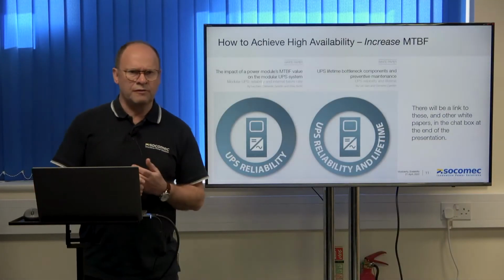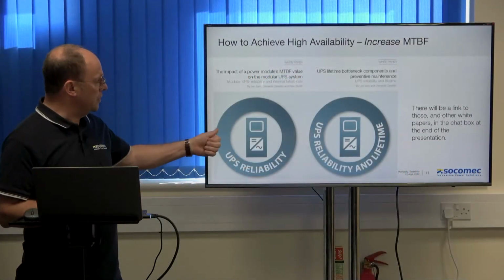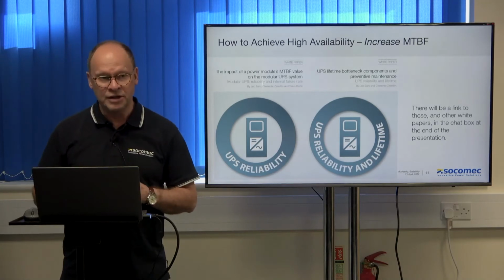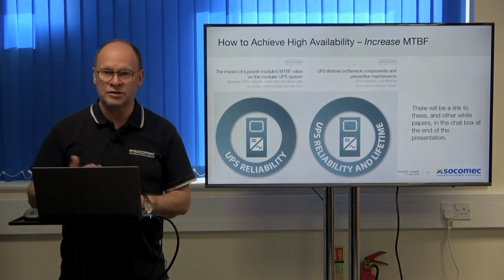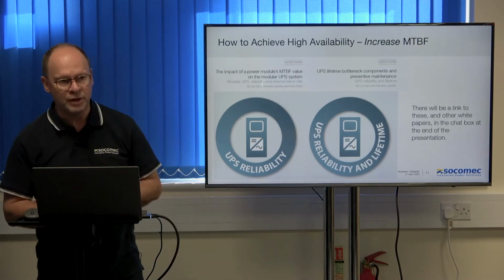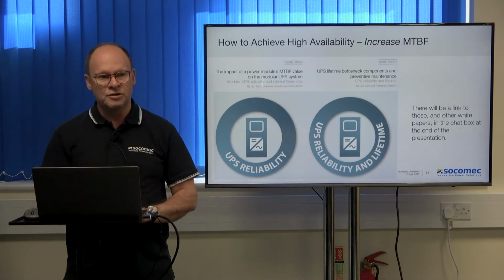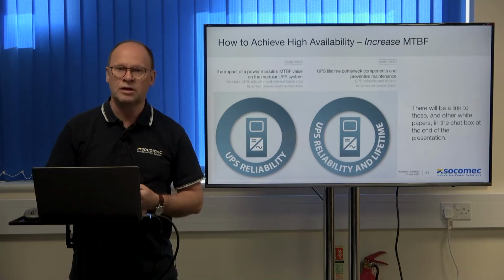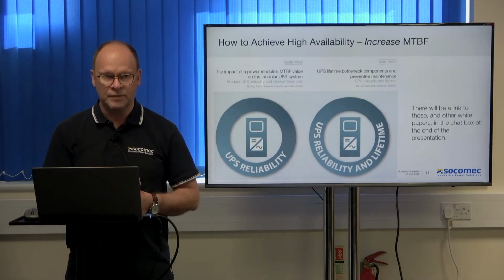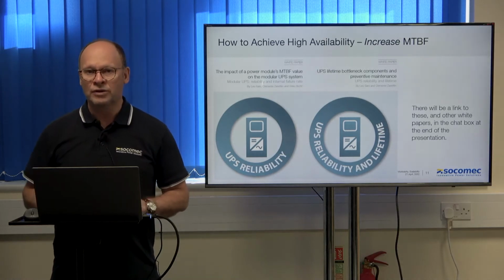So increasing MTBF, I don't want to talk about this in any more depth here because there's a lot of complicated maths and big numbers which are kind of difficult to go through in this sort of forum. But we have got a couple of good white papers which I'd recommend. We can download them from our website, and after this webinar Sarah will email the link to you for those. But just 2 points about MTBF. The MTBF of a UPS system increases by an order of magnitude when you build in some redundancy, and as we'll see later, the cost of doing that with a modular system is much lower than with a monolithic system.